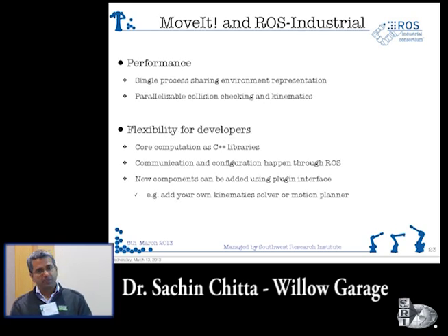And why? From the beginning, when we started looking at MoveIt and started designing it, we looked at doing things the right way in terms of software engineering. So MoveIt gives you very high performance. This has been a key, something that we've emphasized throughout the design process. ARM navigation used to be a bunch of different capabilities as different ROS nodes. In MoveIt, all these capabilities are essentially C++ libraries that you can share and stitch together using ROS. It's got parallelizable collision checking and kinematics, which makes a huge difference once you're starting to do high performance applications.